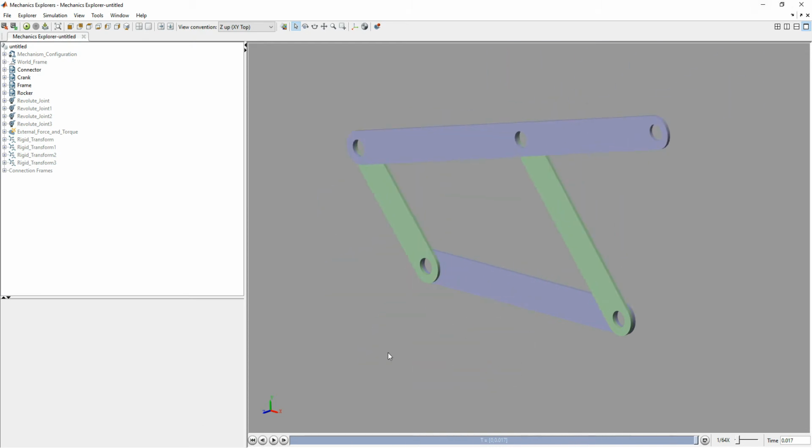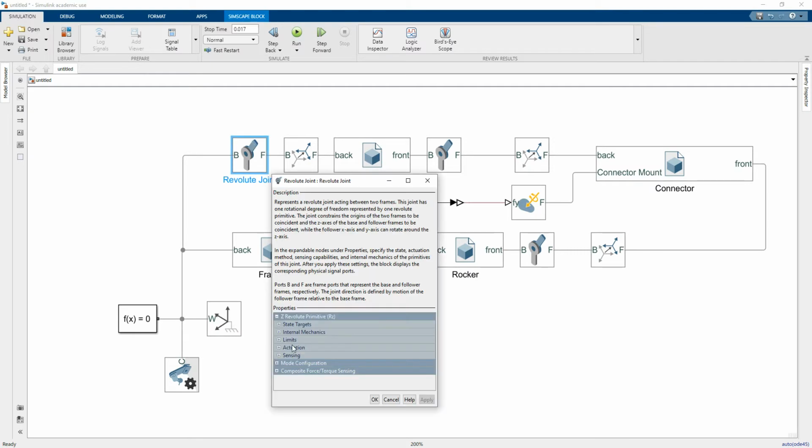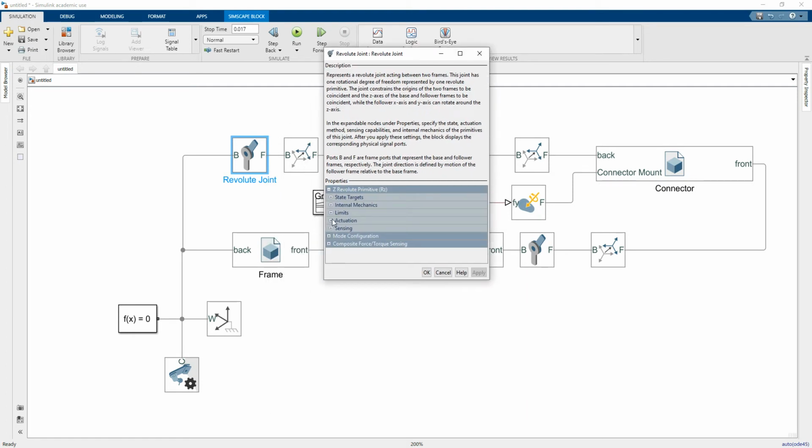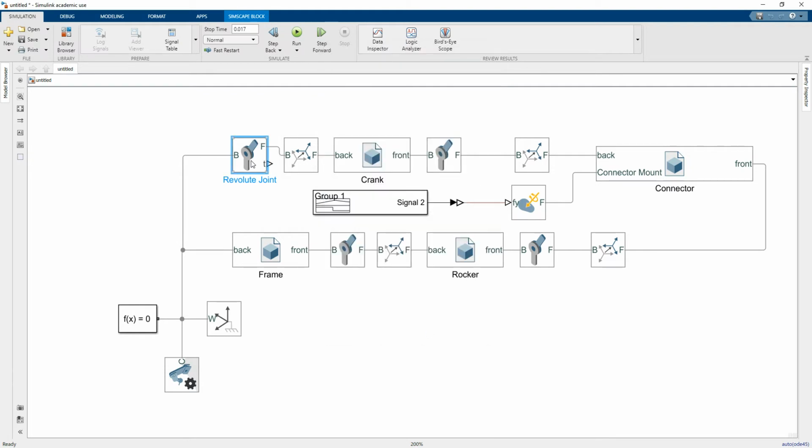behavior operates the same. So what I'm going to do is go into here, I want to know what level of torque it had to put out to be able to deliver something like that. So I'll come down to my actuator sensing, and I'm going to go actuator torque. It will tell me what it needed to be able to do that, and that's where I'm really curious.